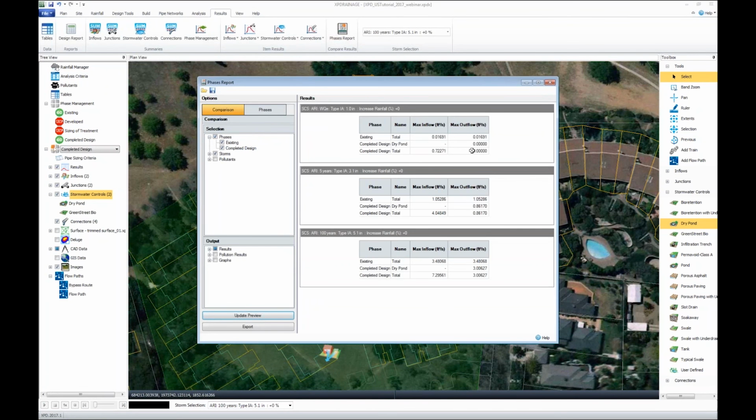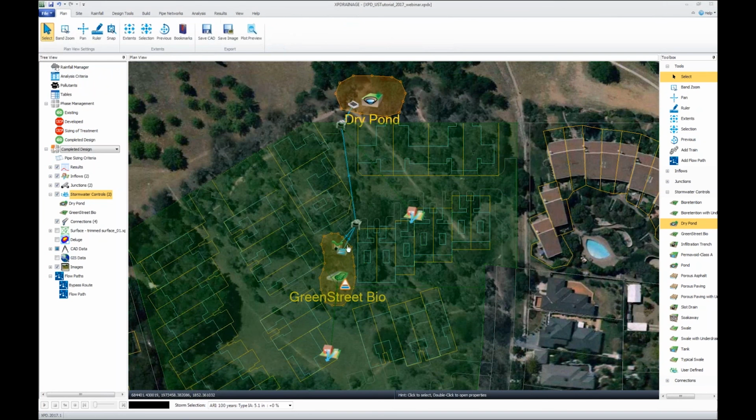Just a tabular water quality event, we don't have any discharge. Well, that's desired, right? The 100-year event, perhaps we have an outflow rate 3.4 in our existing, and, hey, we're under that, right? So we're meeting our different range of events outflow rates. We can make all this comparison and then right-click, save to CAD, export to GIS, export LandXML, push that out, and any updates we make, bring them right back into the software.